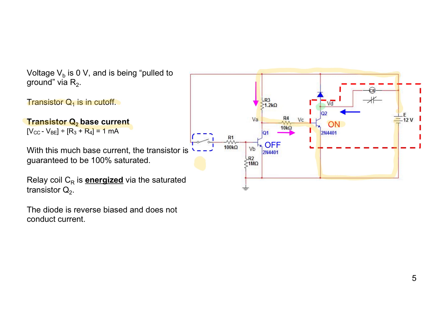We know from earlier discussions that when it's saturated, you're not going to get it down below 0.1, 0.2, 0.3, something in there. But in any way, virtually all of the 12 volts appears across that relay coil. Okay, so it'll probably be like 11.99, right? And a small bit for this Q2 saturation voltage. But anyway, relay coil CR1 is energized. And note that that normally open contact is now being held closed.